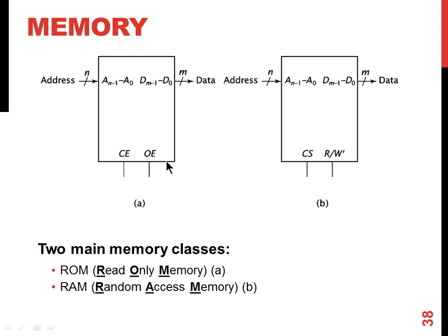Typically, these are the ports or pins required to make the memory work. There is a chip enable to make the memory operation enabled. Output enable is used in case of read operations, reading from the memory. There is a data port. Depending on the width of the memory, the data port will match that value. Then you need an address port.